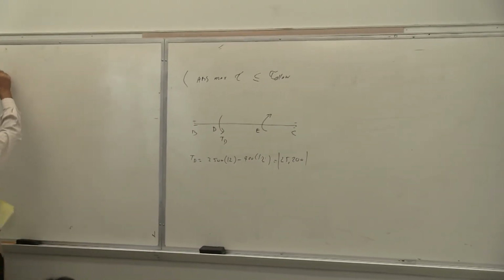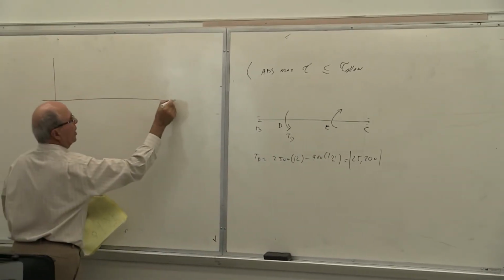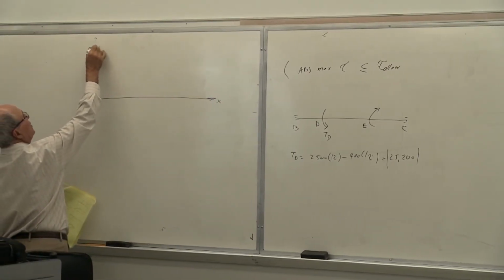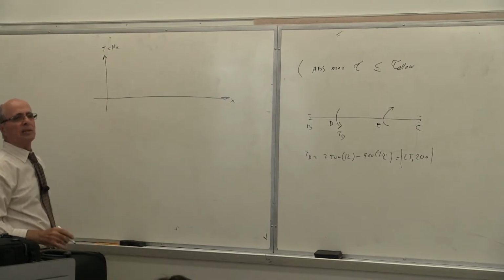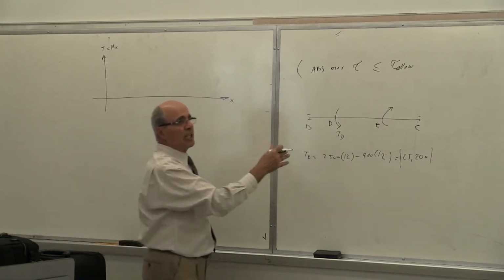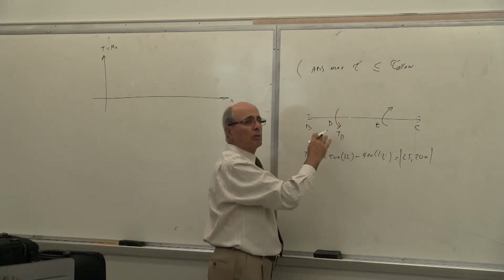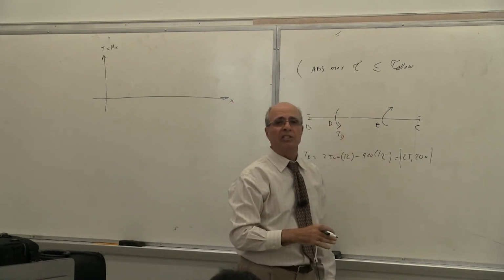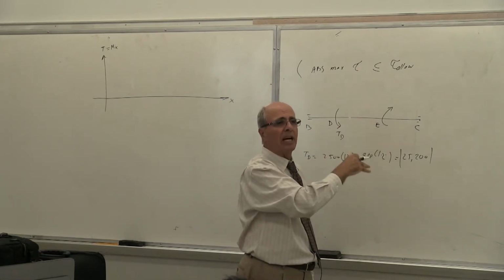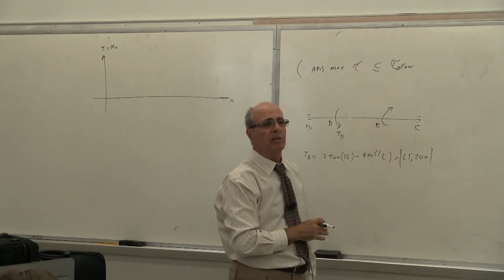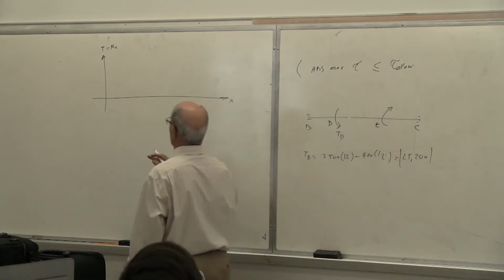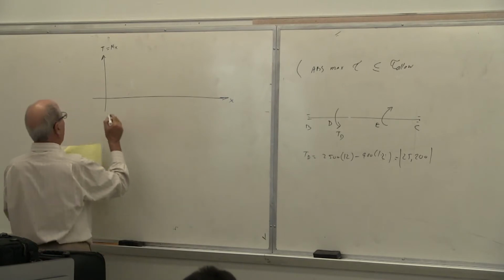Therefore, you are supposed to draw a torque diagram, X versus T, which for this problem is Mx. Is that correct or not? Then, depending on whether you want to go with the action or reaction, or when you cut it you go to the left and right, all of that changes the sign. Is that correct? So you go all action, action, action, or you go reaction, reaction, reaction. Is that correct or not? The way you learned it in ME 218. The sign does not matter, so for the time being, let's stick to one side or another.